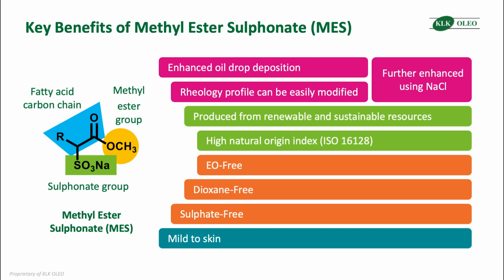Formulators will have to start sourcing for suppliers that are capable of producing surfactants such as SLES with lower dioxin contents. Or formulators can consider replacing their current surfactants with surfactants like MES that does not contain any dioxin at all, and thus completely eliminate this issue for the future.